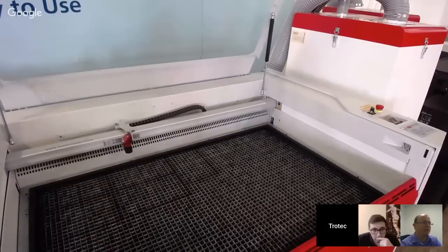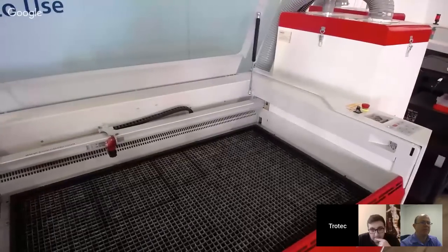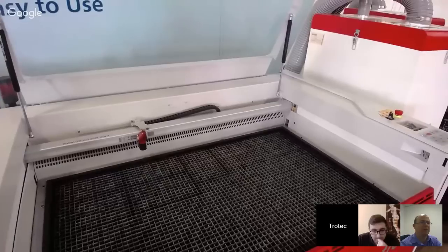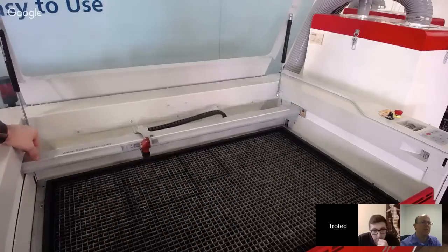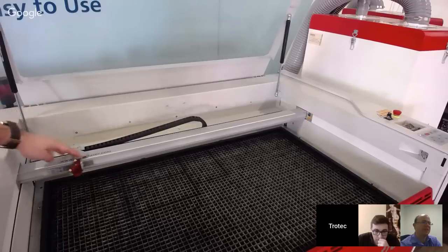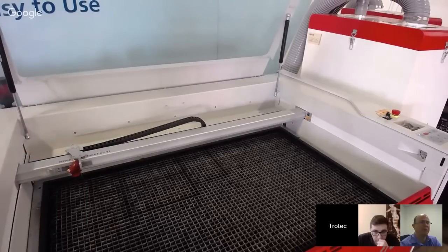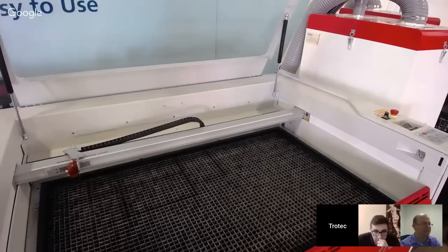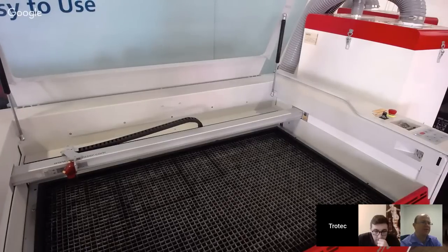The only area where I would not run bottom up engraving would be on engraving rubber for rubber stamps. For some reason, the dust seems to clear out of the sheet better when you are engraving top down versus bottom up. I'm not exactly sure why that is. It just seems to be better for airflow when you do it top down on rubber. But for basically everything else, I'd say there's no reason not to do bottom up.